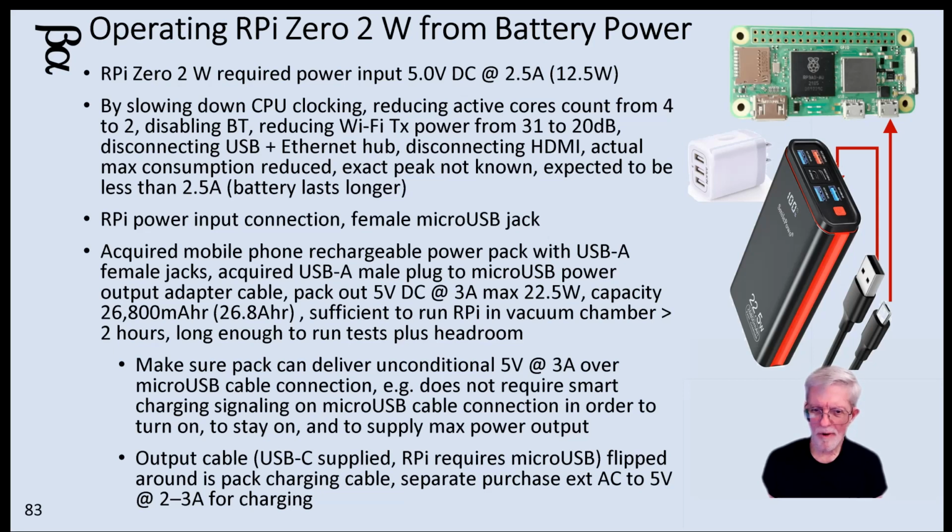And one of these, a battery pack that you might use to charge your cell phone. I just bought one that had the right specifications on Amazon, had it delivered, and that was my battery source. I had to verify everything. The most significant thing is some of these are so smart that if you give them too low a power demand, they won't switch on. Or if they see the power demand was high and then drops low, they'll switch off. So I had to make sure I got a model that didn't have those fancy features.